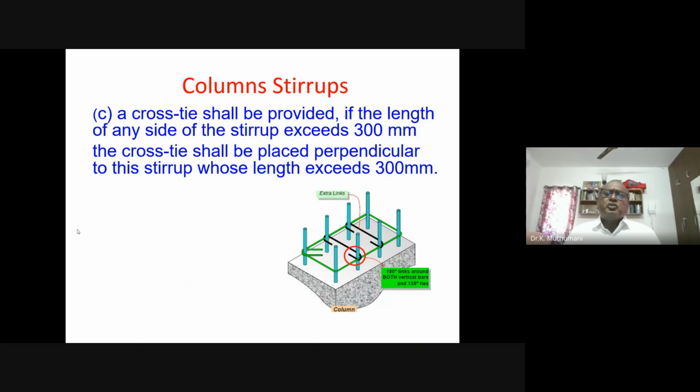So the first point that I want you to note is the column bending moment capacity. Please understand, the column bending moment capacity should be 40% more than the beams coming from the left plus the beam coming from the right. So the column should be stronger. This is a minimum requirement. Then 300 by 300 is still a serious problem, because most of the time we are misdirected by results that come from STAAD.Pro or ETABS. That is the bending moment that comes from analysis. But the bending moment that I am talking about is capacity. Please understand that. Capacity is what you get once you design everything.